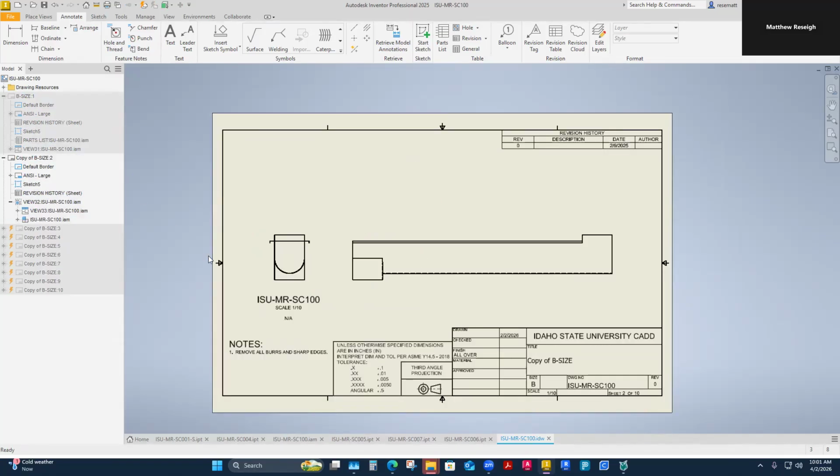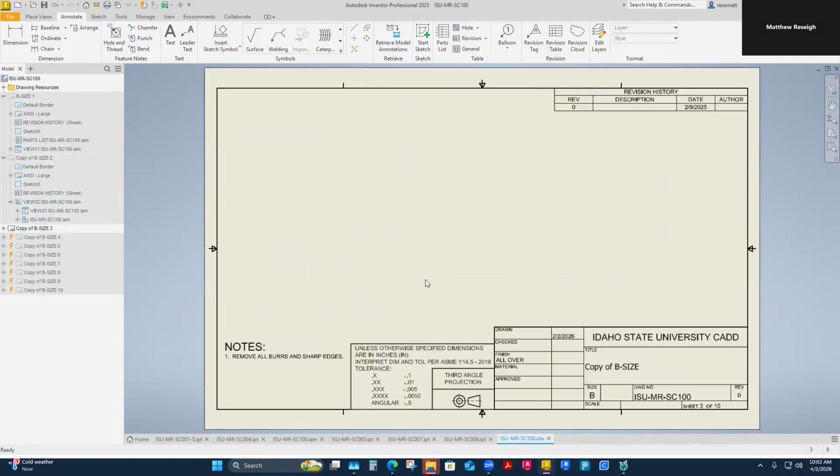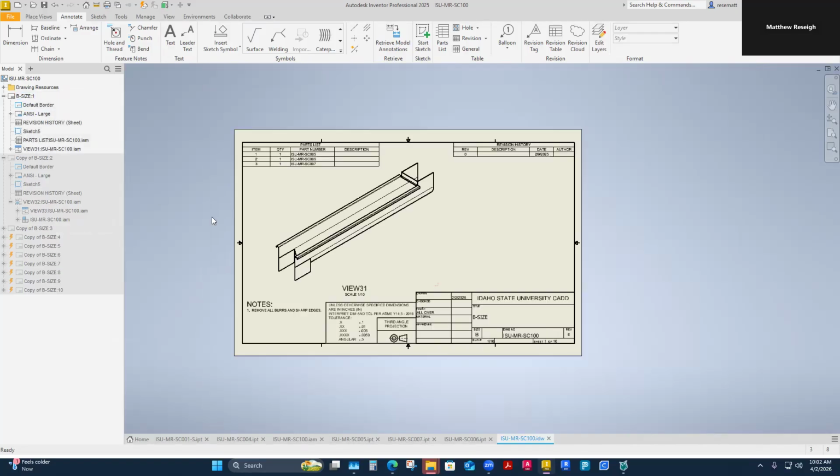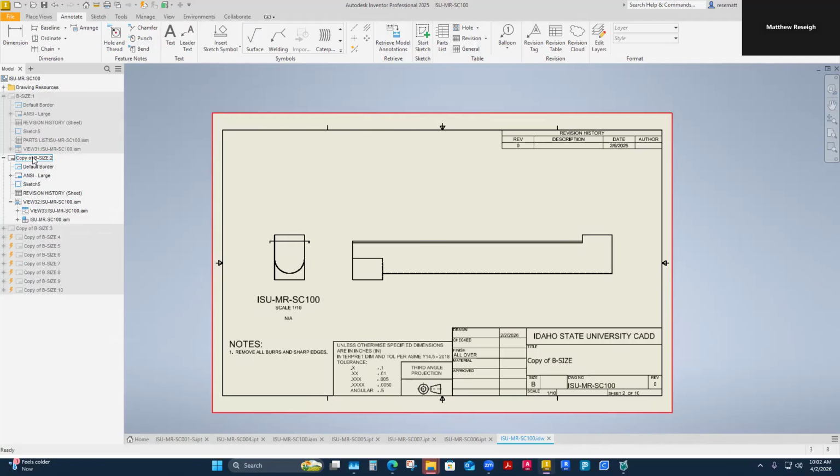This one is going to be starting to be a dimensionable sheet, with dimensions that I can watch as I would build this assembly out. And then I'm going to go down to one more sheet and start placing those individual parts on here. So now I'm going to come into here. This is my third sheet down, and I haven't chosen to name them yet because I'm in this free exploration stage of my prints. But this is how I would organize a print set: here's an assembly, maybe calling out the subassembly parts or even some individual parts that show up in it. Great. And then I'm going to come down here and start detailing out the subassembly dimension-wise.